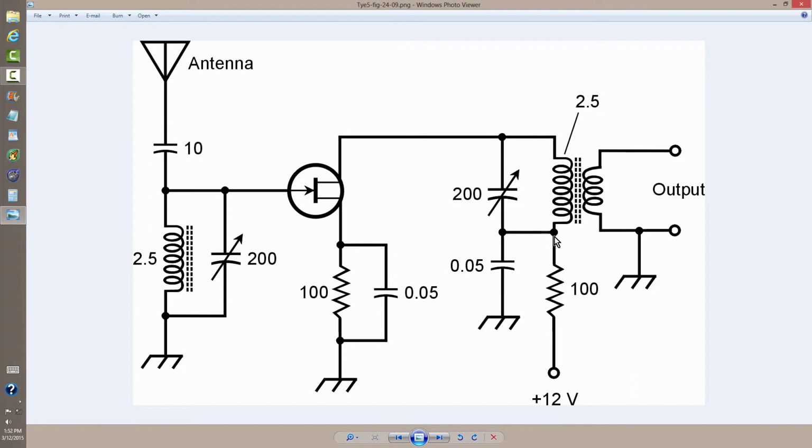And also, you wouldn't want to connect it to any point in this circuit without a capacitor in series with the probe that you use to detect the wave. Otherwise, the direct current bias, this 12 volt power supply voltage bias, would screw up the oscilloscope reading big time. It would displace the wave probably off the screen. So you put a blocking capacitor in series with the probe, probably 0.01 microfarads or something along that line. Then you can connect it either to this point at the top of this tank circuit or this point at the top of this tank circuit.